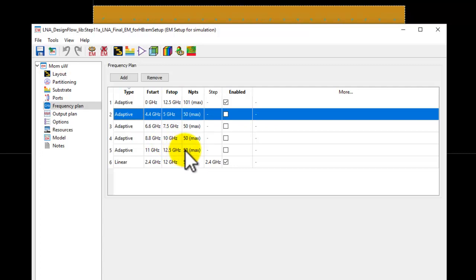Plus, your simulations will run much faster because you're not trying to sweep in an ultra broadband kind of space. All right. So always remember to set up the right frequency segments, which are the ones you're really interested in. Okay, around a DC point, around fundamental points, and the desired harmonic points.